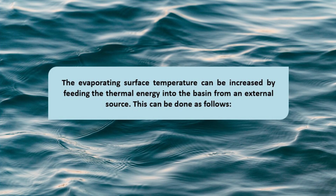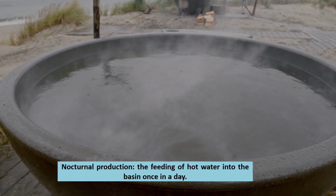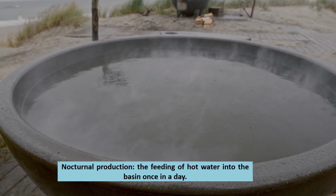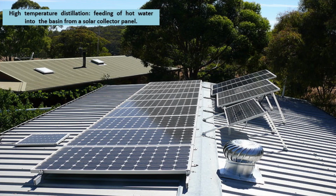The evaporating surface temperature can be increased by feeding thermal energy into the basin from an external source. This can be done, first, by nocturnal production, that is the feeding of hot water into the basin once in a day. Second, by preheated water application, that is the feeding of hot water into the basin at a constant flow rate. Third, high temperature distillation, which means feeding of hot water into the basin from a solar collector panel.